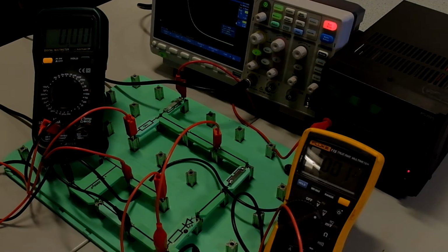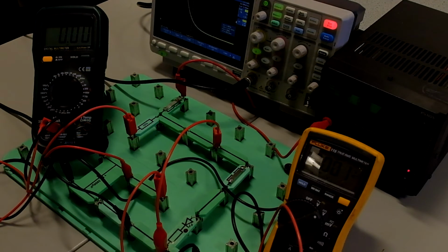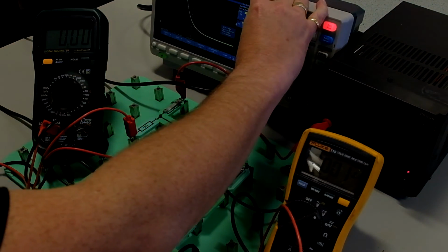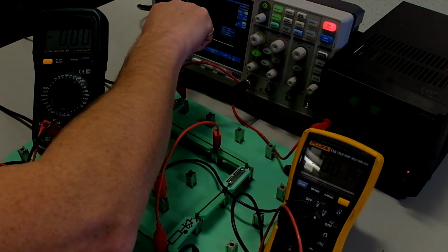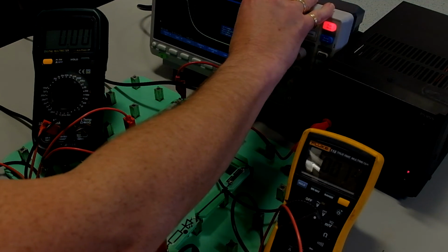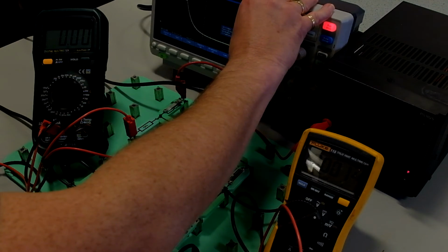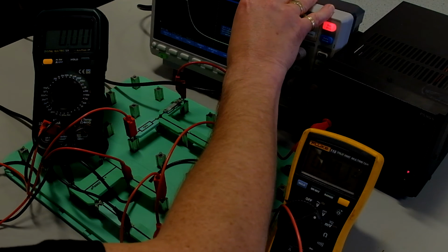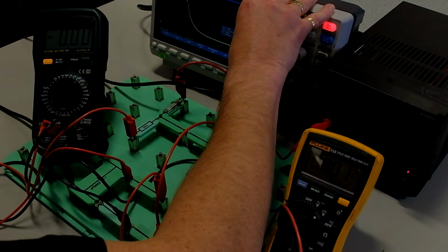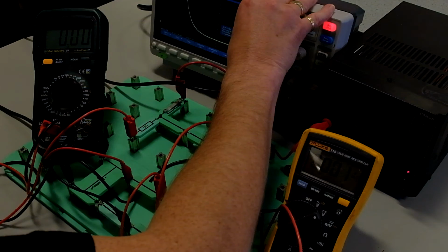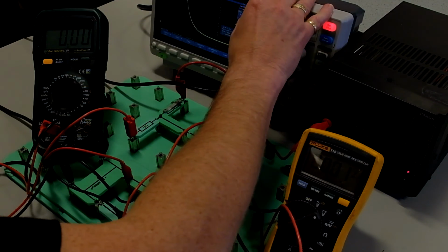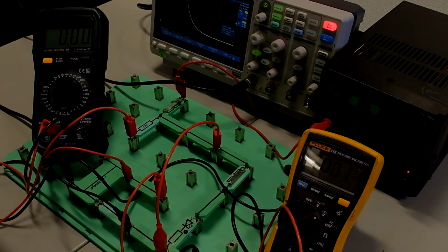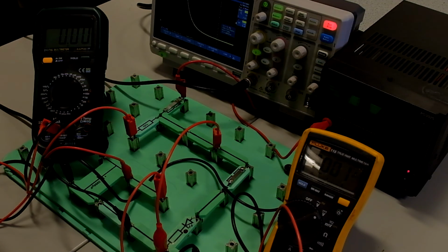It's a little bit more than expected, but it does verify that the voltage drops very rapidly, and then it will take 10 seconds to get anywhere near down to 0 volts. So we're really talking about down here. I would say that's really taken about 12 seconds to get down. So we have verified the time constant.